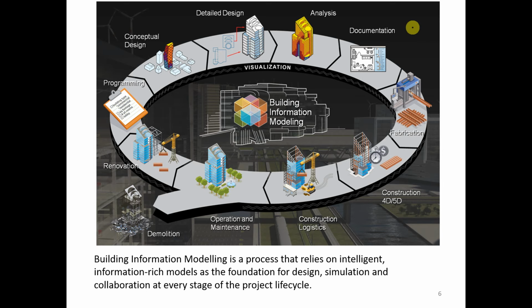They link the architectural model to a mechanical file, and we're still using Revit, so they link in the architectural model, and then they start overlaying all the air conditioning, electrical and plumbing within another file in Revit. That can then be handed over to the structural engineers, and they can overlay all the structural aspects of the building in another file. Now these three files can then be pulled together into another piece of software called Autodesk Navisworks.